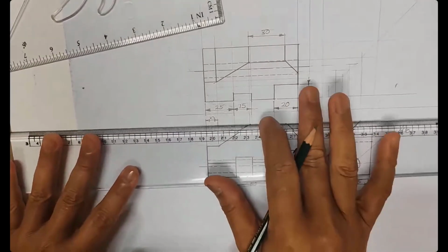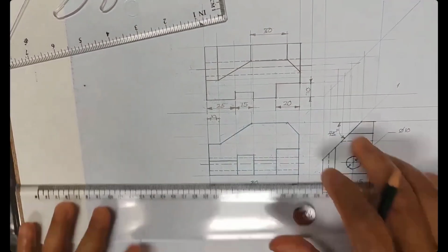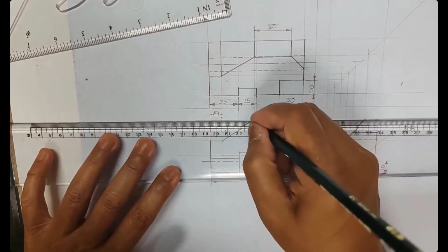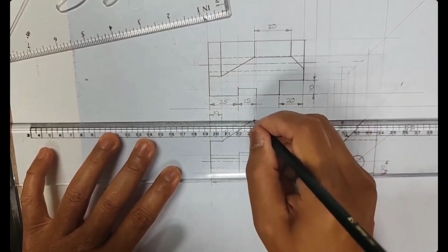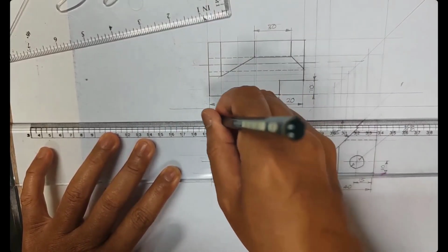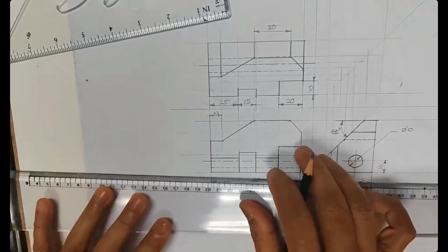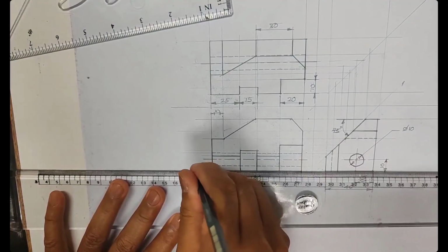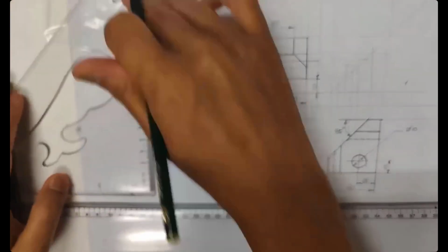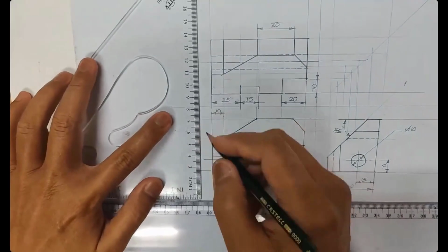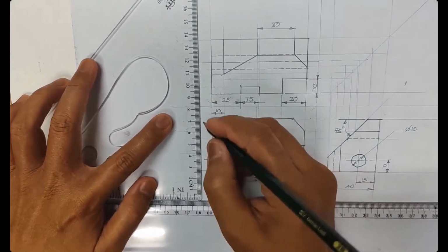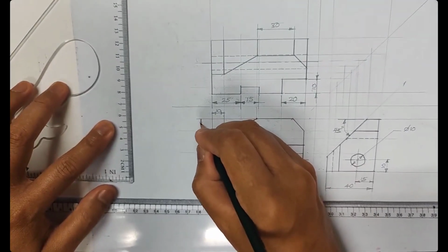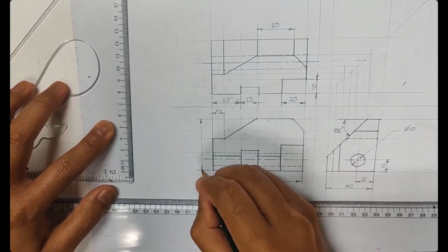Alright, in the front view I can make the maximum because I don't already have a leader here for the diameter 10 of the hole. So I can make my extension line, not touching the corner, gap 1 millimeter, about 2 letter height from this corner to this corner. The extension line should not be too close to the object, at least 2 letter height. Okay, so this will be the extension line, then make an arrowhead, 3-1, right? Not too bad.